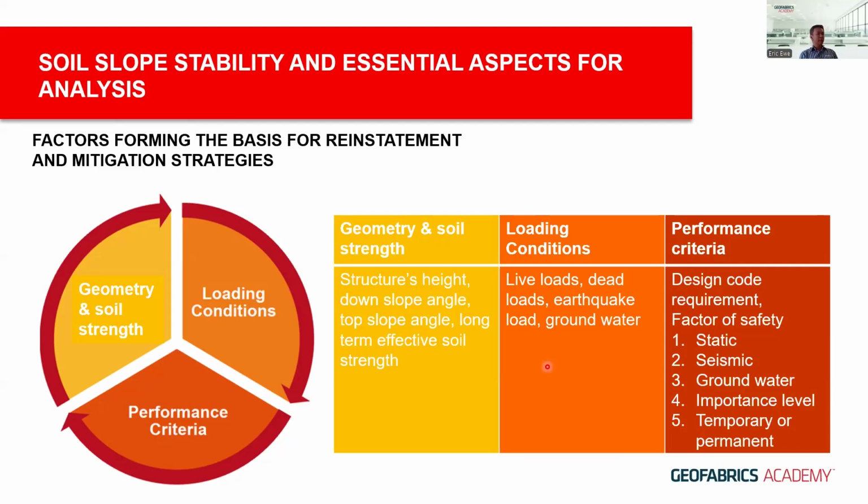I think this governs the entire scheme of reinstatement, and how elaborate the scheme or the solution would be. It is governed by certain territorial code type of guidance, such as councils or roading authorities or certain design code requirements in terms of factor of safety. And they can be the static load conditions, seismic, groundwater, importance level, temporary or permanent.